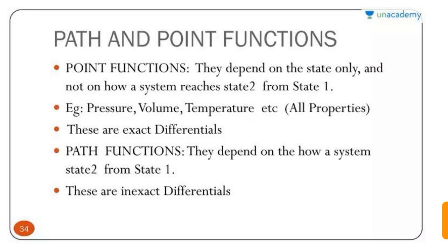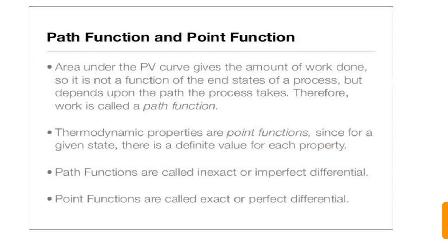They depend on how a system moves from state 1 to state 2. These are inexact differentials. The area under the PV curve gives the amount of work done. So it is not a function of the end states of a process but depends on the path the process takes. Therefore, work is called a path function.